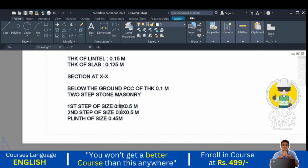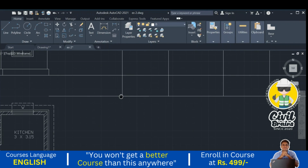So what is the excavation width? If you take exactly 0.8 meter, then it is very difficult to construct. If there is no projection, it is very difficult for the labor to do the masonry work. So we can consider it 1 meter. So 0.1, or 100 mm extra offset we are taking, so that it will be easy to do the masonry work.